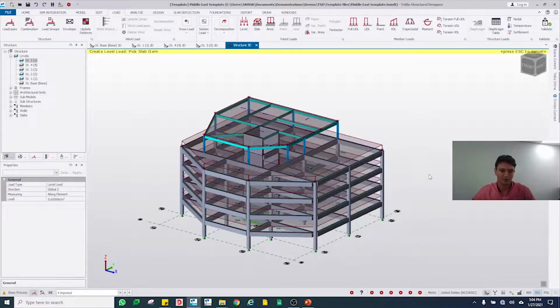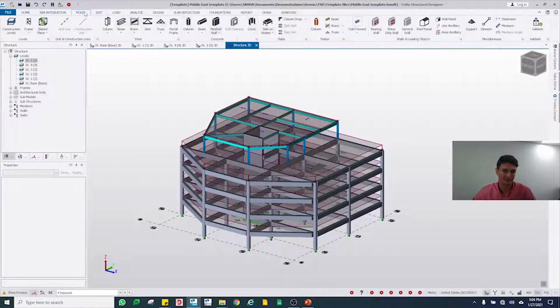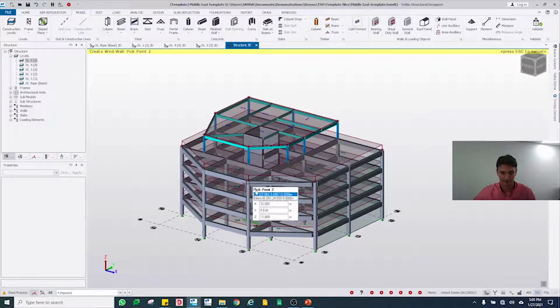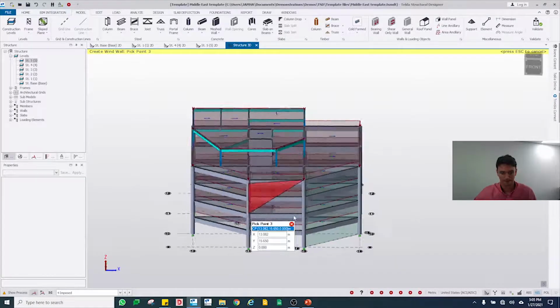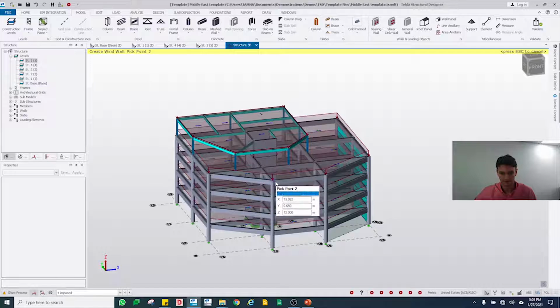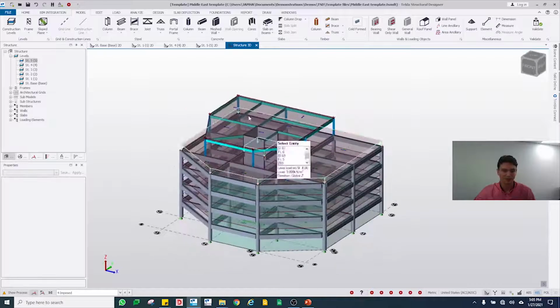So then just to quickly show you how we apply wind load. So we have in the model tab these options for panels that I mentioned. So you surround your structure with these wind panels, and I'm not going to do the whole thing, but just to give you an idea of the approach. So you draw these panels around, and then if it's a flat panel, you choose the roof option, and then you run the wind wizard.